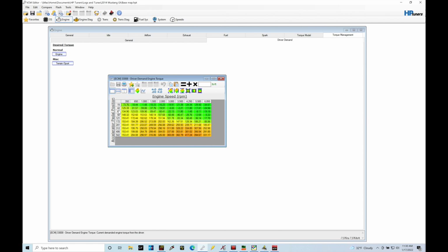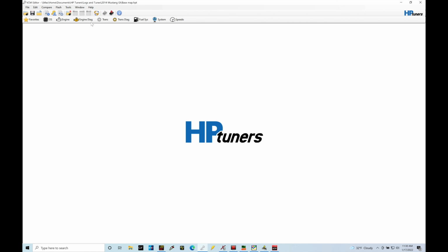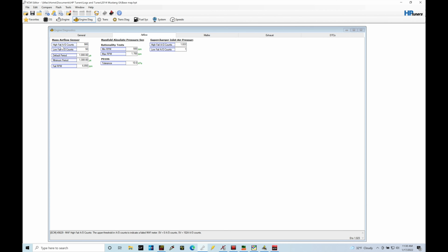We can conceptually understand that. The unit scale is actually between 0 to 600 in the accelerator pedal position AD counts. So that's how it's going to look at that 0 to 100% movement range of the accel pedal and translate that to AD counts. Let's close this out and jump back in. It's the same idea here as our mass airflow AD counts.